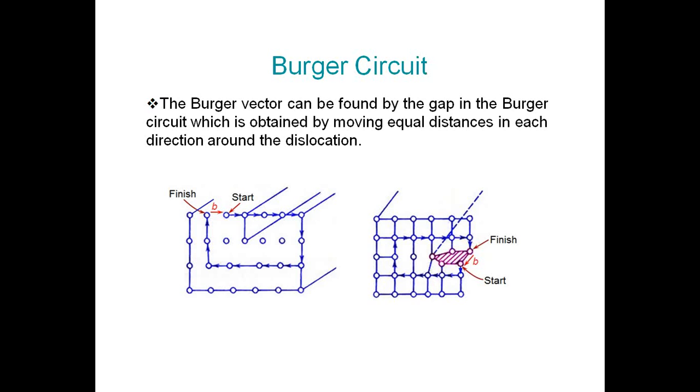This Burgers vector is formed by drawing a vector of lattice translations, that is lines around the boundary of equal length on the parallel sides. For a perfect lattice structure, the Burgers circuit will form a closed loop. In case of a defect, the Burgers circuit will fail to close. So here you see, if it is a perfect crystal structure, this circuit or loop will be closed perfectly.